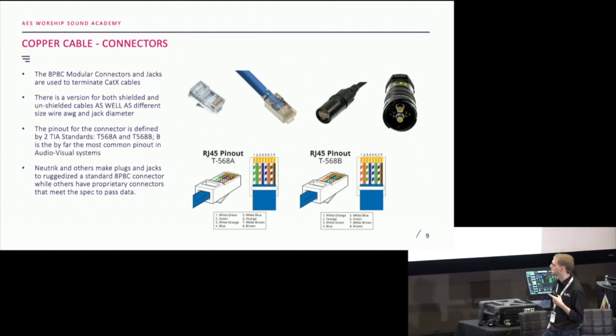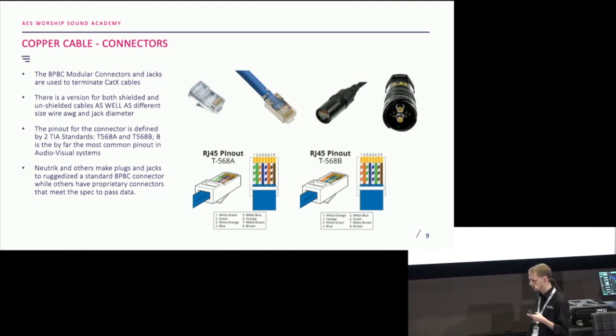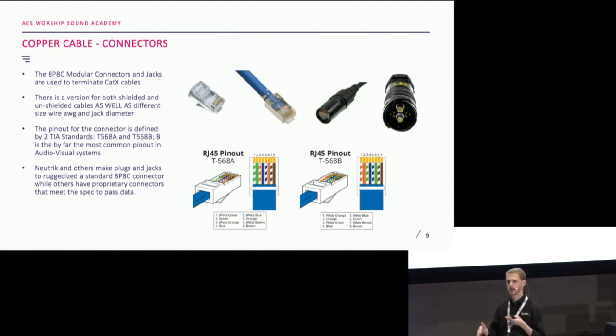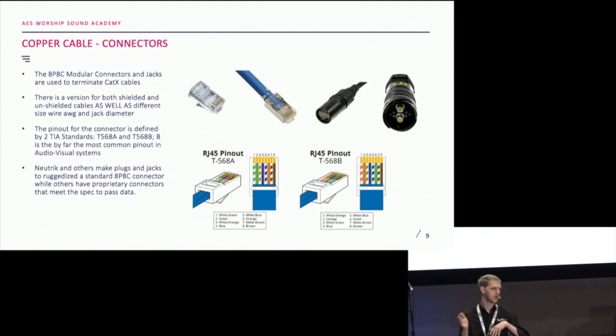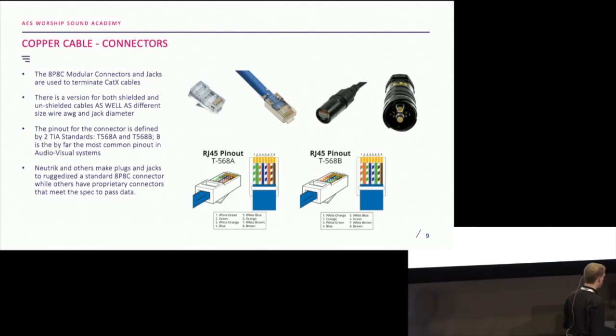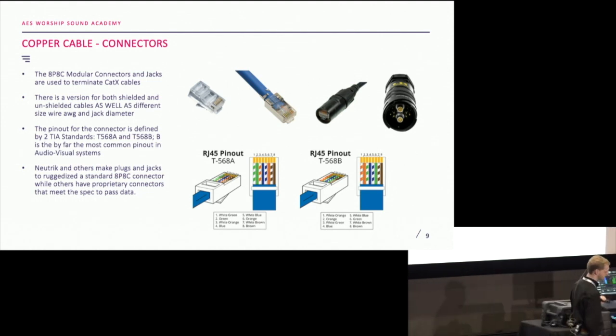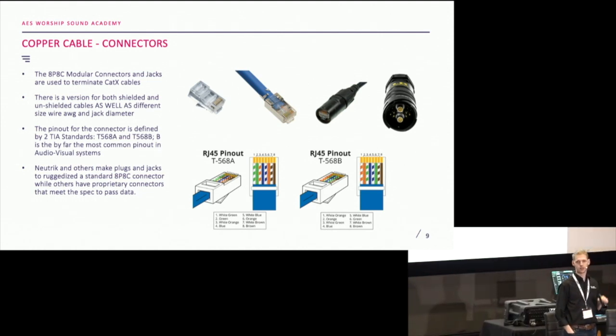The Cat5, the Cat6s, there are higher ones, Cat7, Cat7A, Cat8. None of those are really standardized. They're just manufacturers have said, here you go. But 5E, 6, and 6A are kind of the standards that you're going to see. And the biggest point that leads us into the next thing is that you've got a limit of 328 feet or 100 meters. So if you need to run farther than 300 feet, you're going to run into problems with copper. So that brings us to fiber.